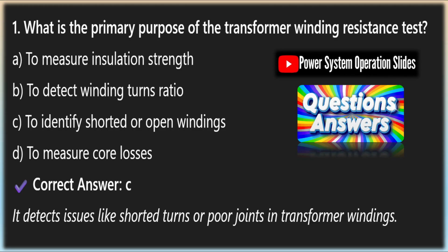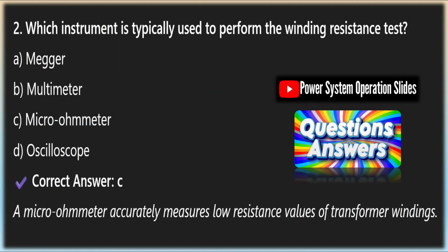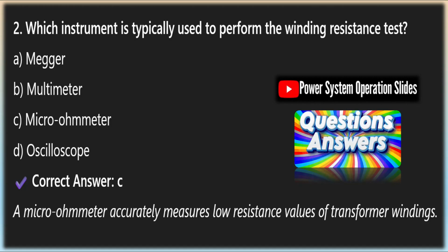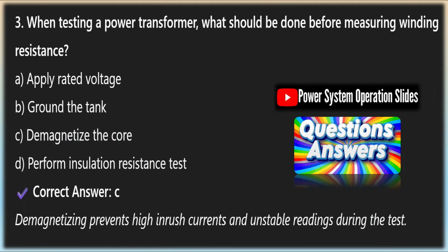Evaluation of results, pass criteria: phase resistance deviation less than 2% for the same winding. OLTC step variation: smooth variation, no jumps. Resistance should align with factory test reports corrected to 75 degrees Celsius. A sudden increase suggests a possible loose contact or carbonized joint.